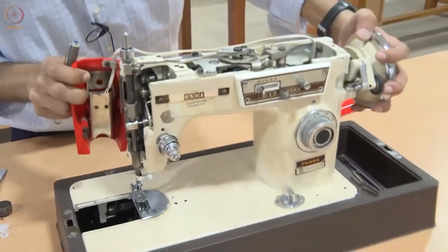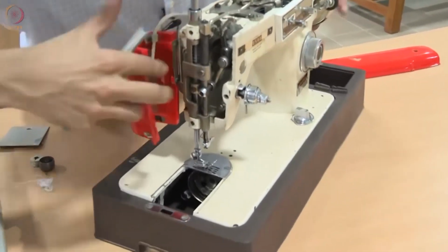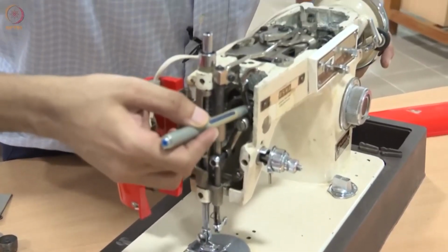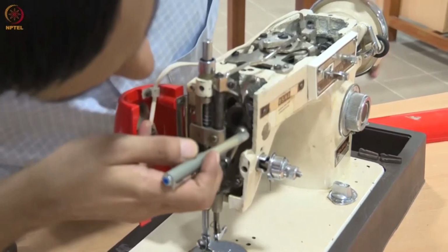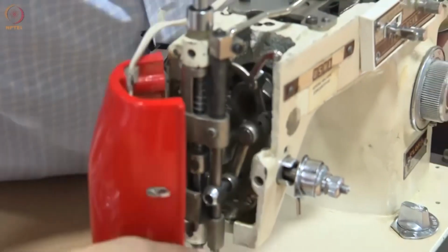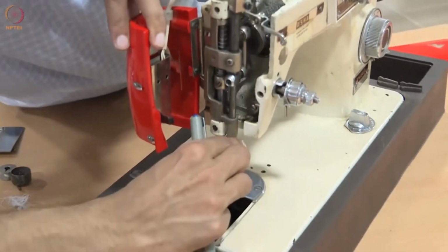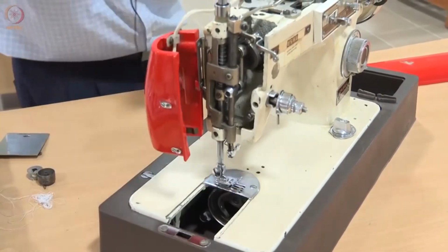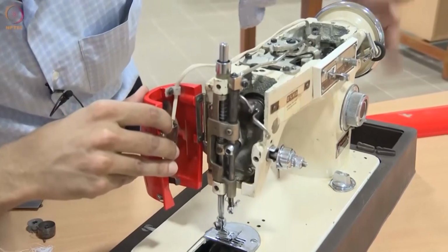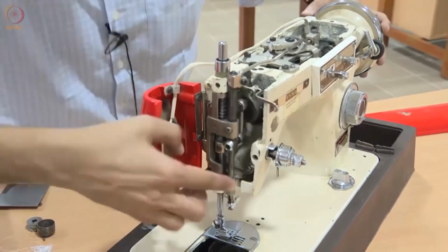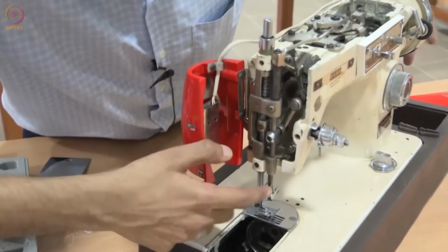Similarly, you have another crank here. So this is another crank. There are actually two cranks in this case. They are offset. So you have another crank, and then you have the sliding mechanism. You can see I can actually back drive the mechanism. But now, this is called a singularity. So I can comfortably drive the mechanism, that is, if I keep the crank as the input, I can keep driving the slider part easily.